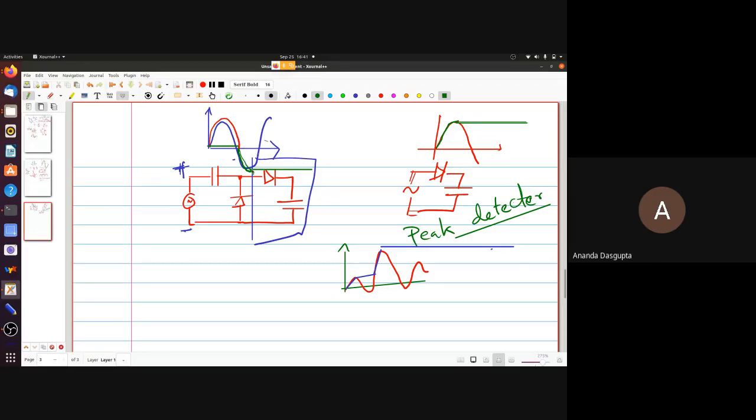And that means that the capacitor will always have a large voltage, minus Vp. If that happens, what is the voltage here? That's the voltage at the input minus the capacitor voltage. And since the capacitor voltage is minus Vp, the voltage here will be the input voltage plus Vp. And that means after this capacitor has charged up, the entire output, essentially the entire input, will be pushed up by Vp. So it will go like this. From that point on, it will go up and down like this. That's how the diode clamper works. Okay?